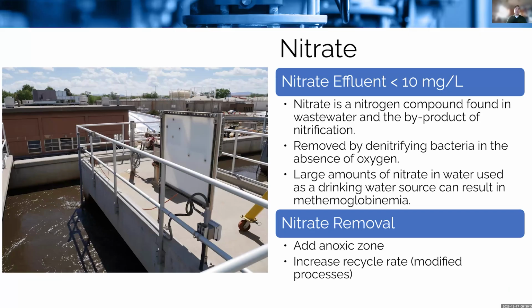Now, hand in hand with that ammonia is our nitrates. As you treat ammonia, you produce nitrates. And the nitrate, as we mentioned last time, if you have excessive amounts of that in your drinking water, it can result in methemoglobinemia, which is that blue baby syndrome.